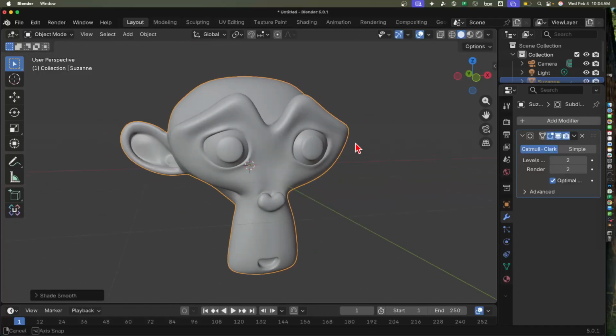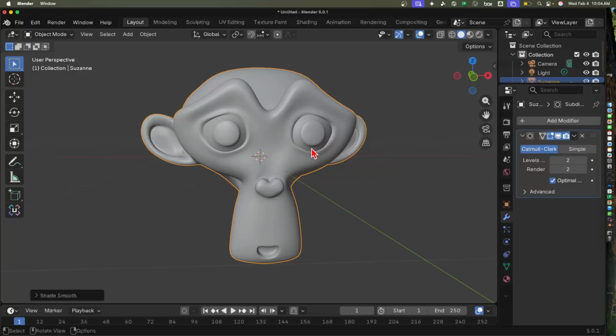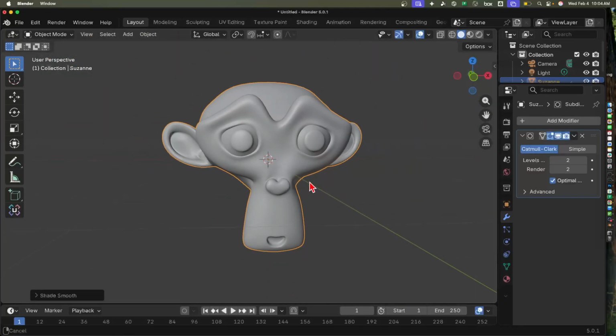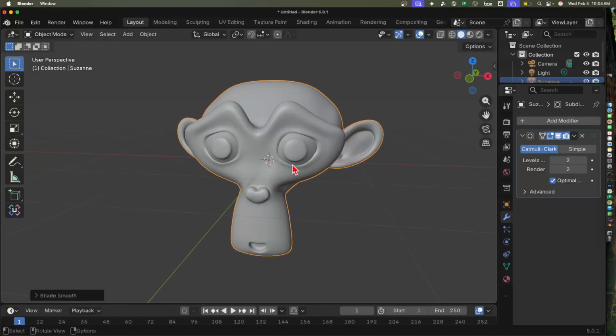Okay, middle mouse button gives us the orbit, middle shift pans, and middle control zooms. It will be painful, but you will figure it out. Hopefully you won't have to do that much. This is only a week-long assignment. It should be a strong assignment.